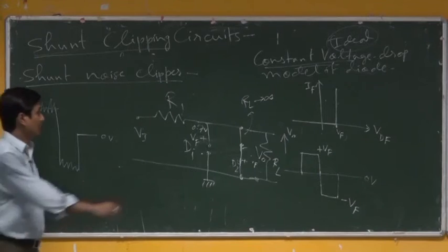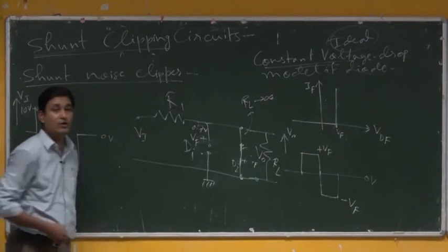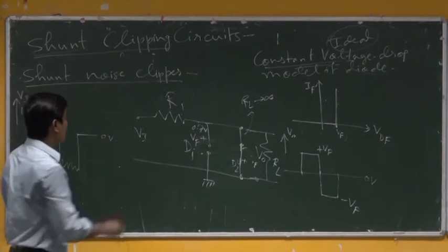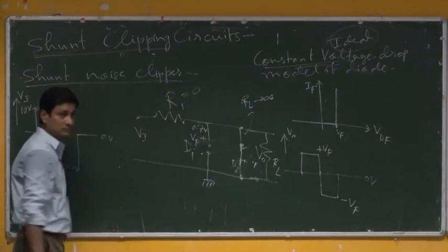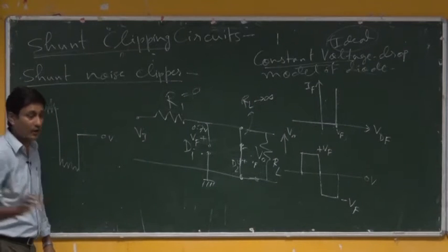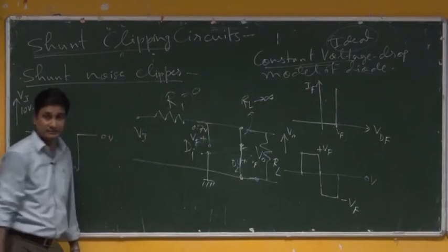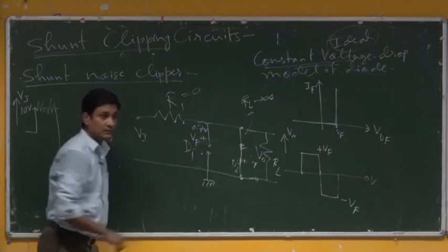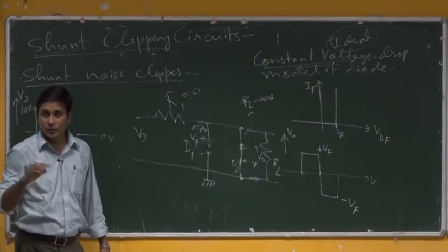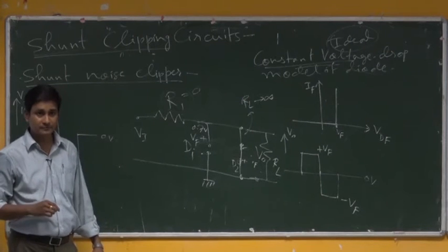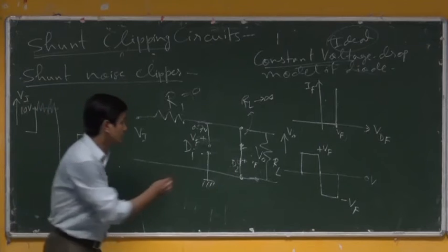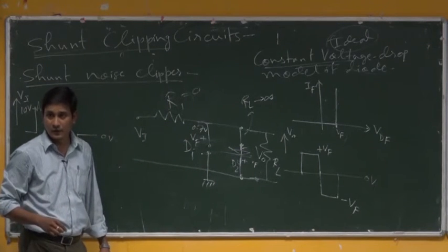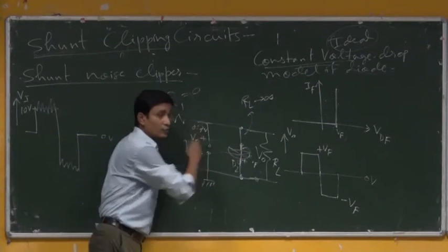In that case, if this R1 would not be connected to the circuitry, say this R1 is equal to 0, means you didn't connect any R1, but directly you have short-circuited it. Only the diode was connected here. In that case, current would flow infinite. Through which? Through the diode which was connected to it. So, in that case, this diode could be burned.